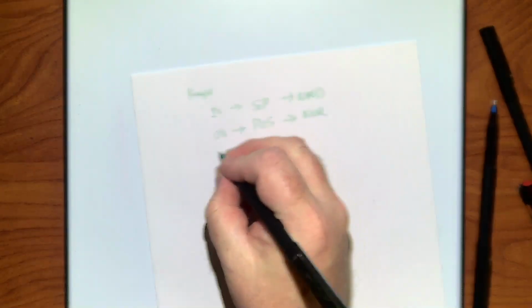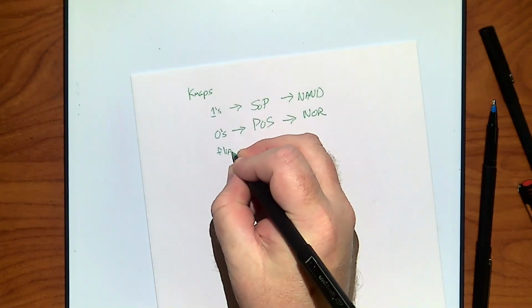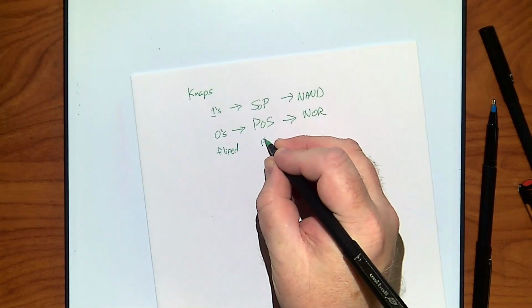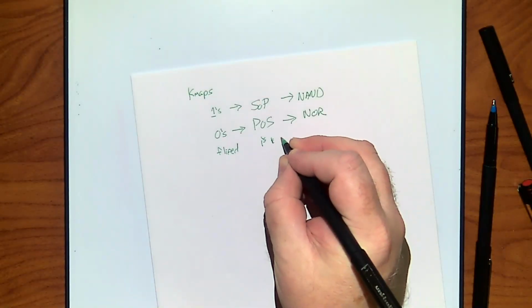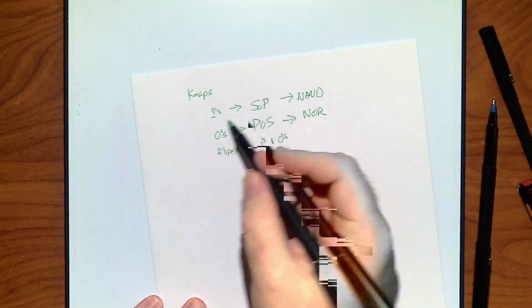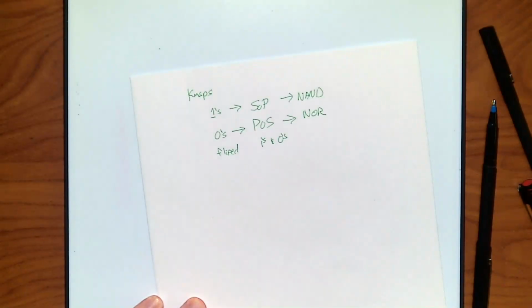So I'm just going to kind of combine these and say, what if I flipped my ones and my zeros, right? And then I could still do each of these, but this is kind of a negation. Now I can do my encircle ones and circle zeros just like I did before, except they're now flipped. What I would get is the negative of my function.